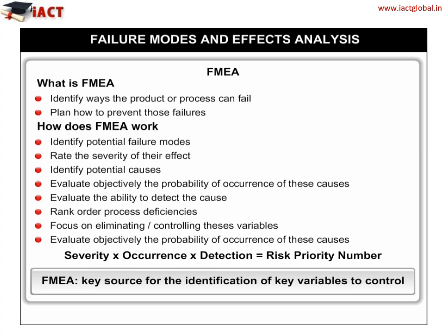It is important to remember here that FMEA is not a tool to resolve the factors that cause errors. It is a useful tool to identify potential factors and prioritize the order in which the evaluation of the factors should be done. Ideally, FMEA should focus on the part of the process that has the highest scoring X variables from the YX matrix.